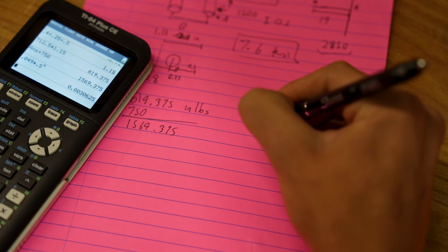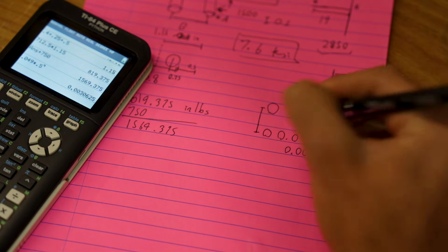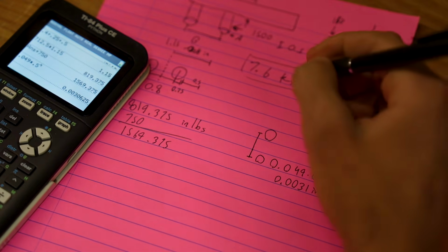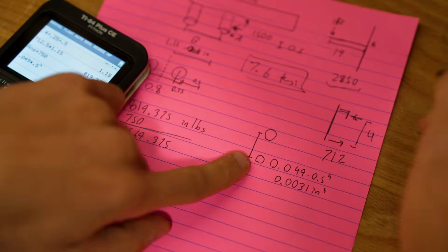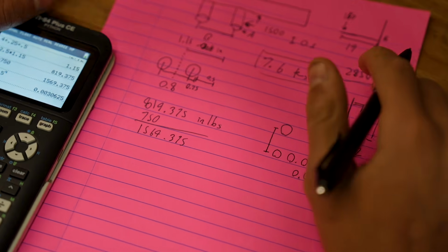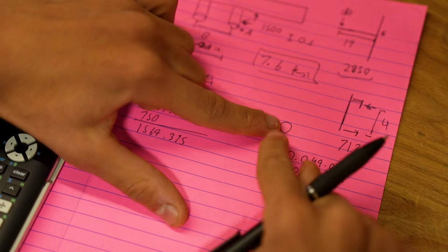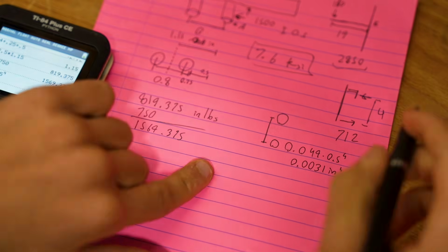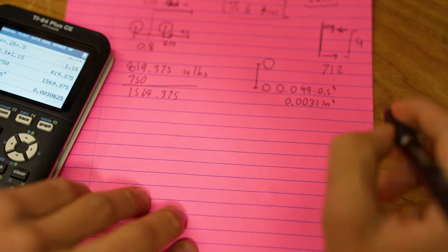We're then going to use what's called the parallel axis theorem. If you haven't taken physics, it's a way of separating bodies and weighting their distance. As these become further apart, intuitively you would think that they help each other resist bending more, and that's actually a squared relation.